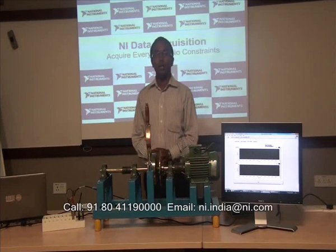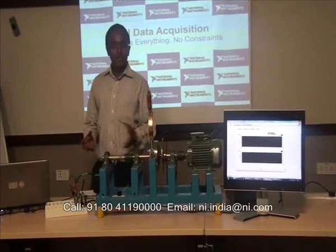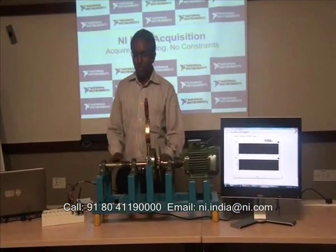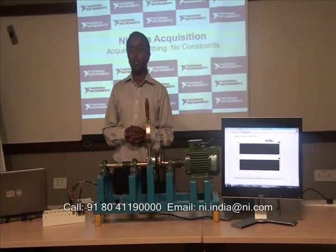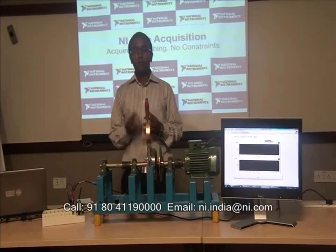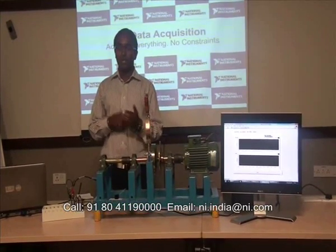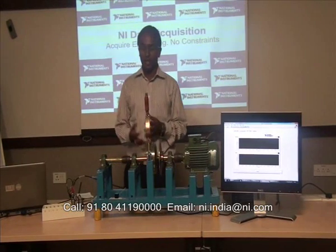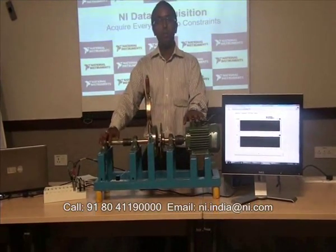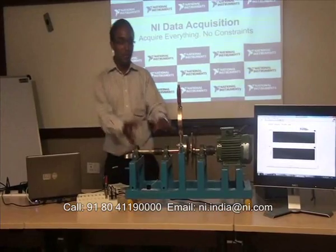So let's see how simple it is to use NI DAQ hardware using NI's driver and application development environment software, that is LabVIEW. Here is a setup which has been put across for today's demonstration, which we call machine condition monitoring. Machine condition monitoring is a very important application in structural health monitoring in mechanical industries. This is an application where we do preventive and predictive measurement of any machine to find out where a fault can arise in future, or to cut down the cost because of those faults. In this application we have a machine to replicate the actual machine environmental conditions of an industry, and we have our devices here to capture that vibration data